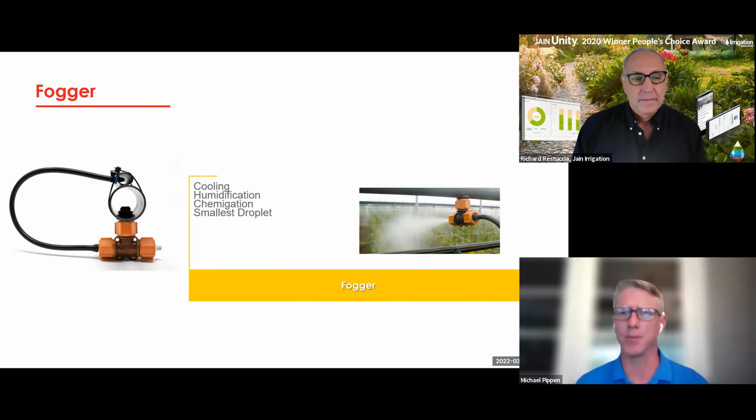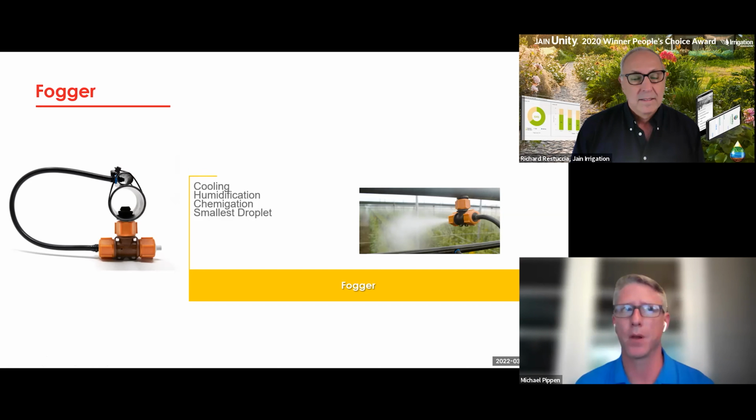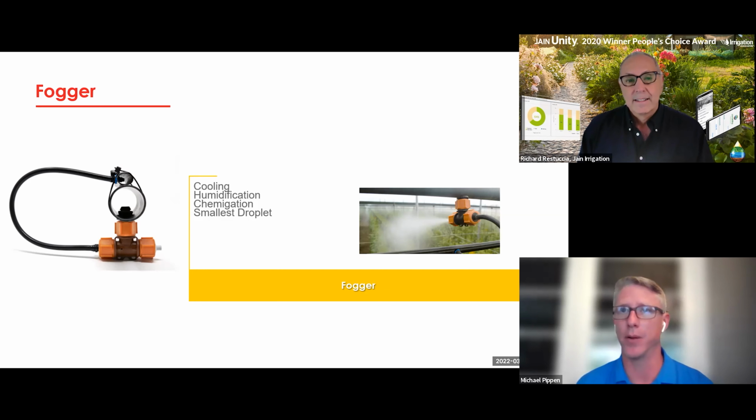Not a whole lot. It's more about a volume issue. You can see that this pipe for the air is a lot bigger than the pipe for the water, right? And so just from a design standpoint, we want all these devices, all these foggers, to have the same air pressure, right? And so air is a little bit harder to manipulate. It's not quite as forgiving in a pipeline design as water is, right?